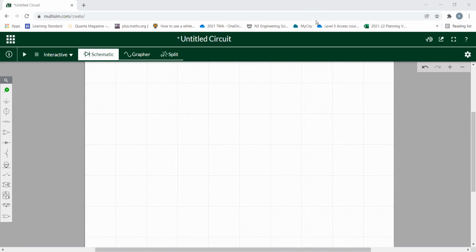provide a function of only allowing part of an AC current to pass through, in this case, only the positive part. In and of themselves, they're not of much use in electronics, but we can use a slightly more complicated version of this. I'm going to do that later in the course to make a circuit which goes some way towards converting AC into DC current.